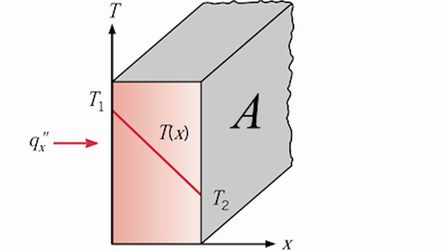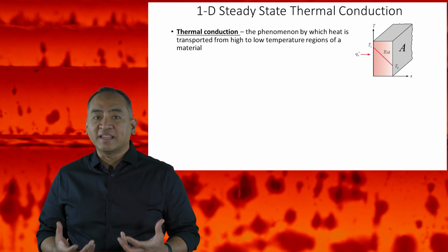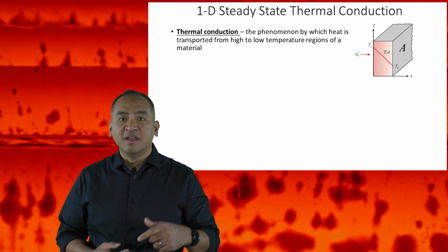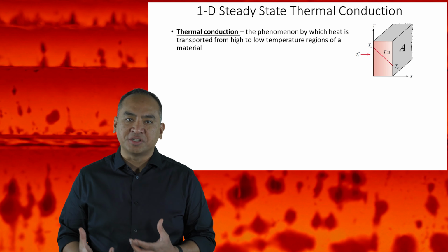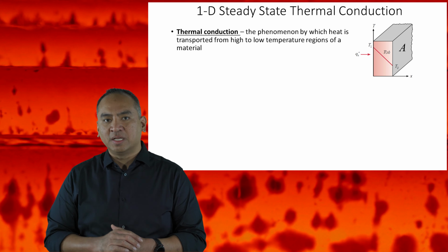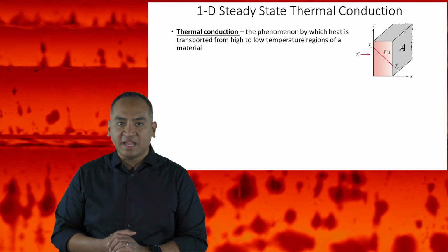If the thermal properties of the material are uniform throughout, and there is nothing inside the wall that is generating heat or acting like a heat sink, and we assume that conduction is only happening in one direction, which is the X direction, then a graph of the temperatures along the plane wall in the X direction is linear at steady state.